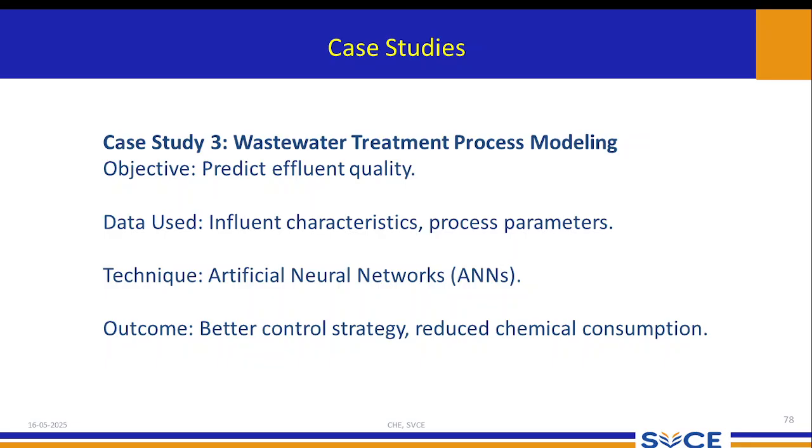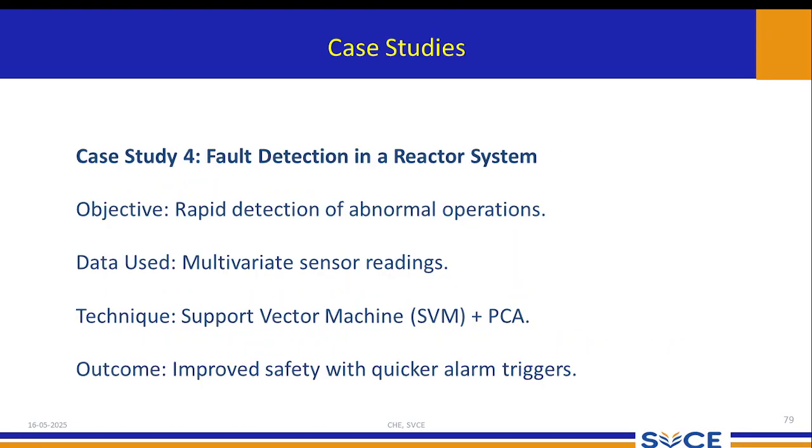By adding ferrous sulfate and hydrogen peroxide, there is one disadvantage on the other side: iron precipitate will be formed, and the total suspended solids will increase in the process. How do you manage that? We need to know the domain knowledge, and also what needs to be carried out, what should be the outcome, and how these parameters are corrected. If you know this, that will help you use the machine learning model to control this strategy. So this is the idea.